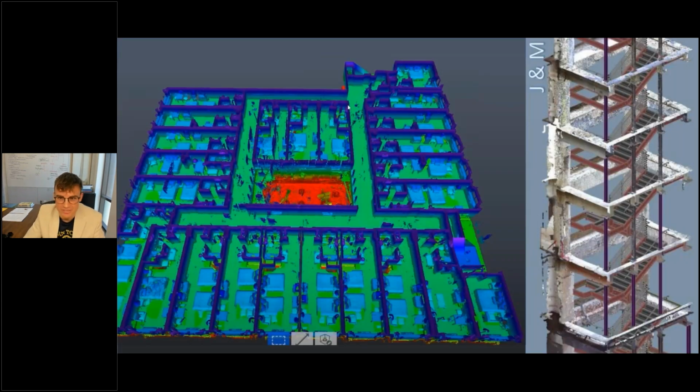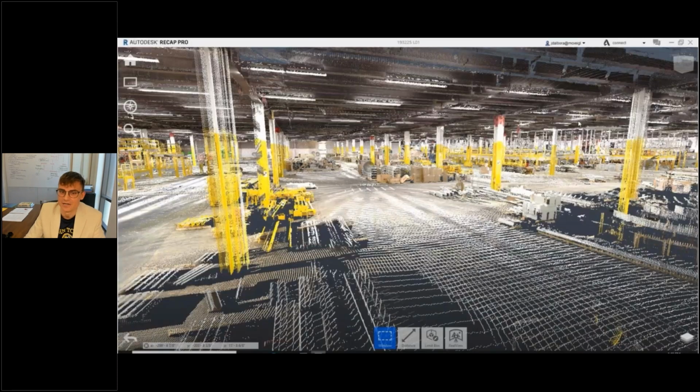Repetitive geometry. For example, here we have a hotel where each room is the same as the next. How does the cloud-to-cloud know what room the scan was captured in? They can't know. And the same problem with the flight of stairs on the right side here. Each flight of stairs is the same as all others. And here there's repetitive geometry and poor spatial constraints. And so this kind of environment will also be problematic for cloud to cloud.